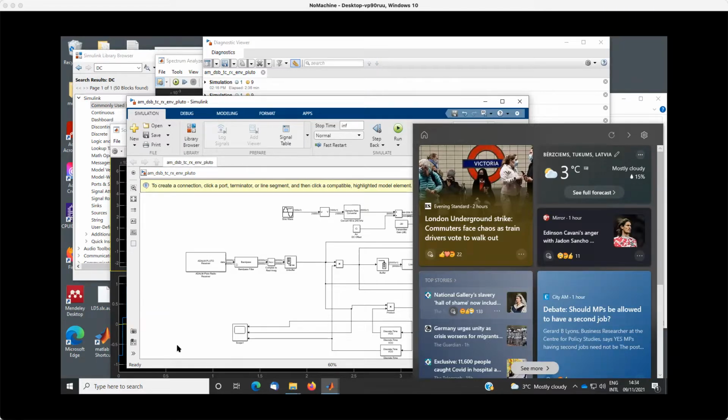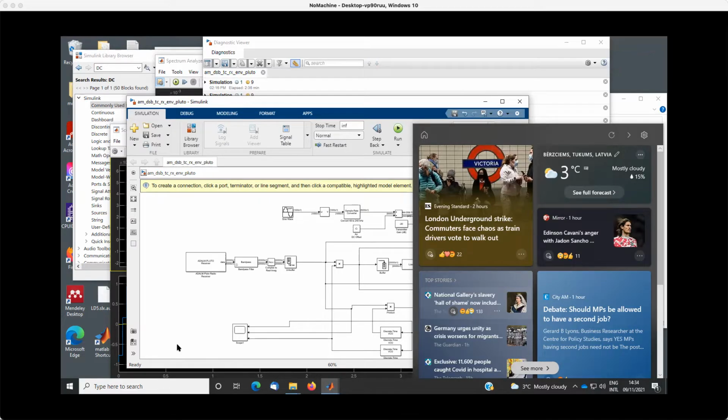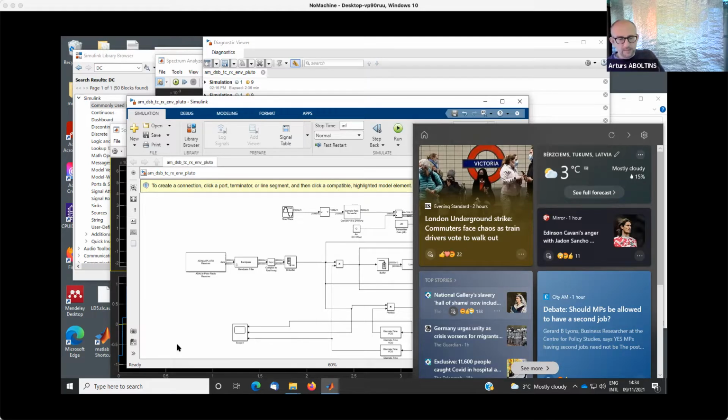Okay. You can use the derivative, you can use the second VCO, and this is up to you. Last time we were using the derivative and it was working as well, but because the nonlinear distortions for the derivative are much higher, I believe it will make it more difficult to tune, and maybe it decreases quality. However, I think in our case, it's not a big deal.